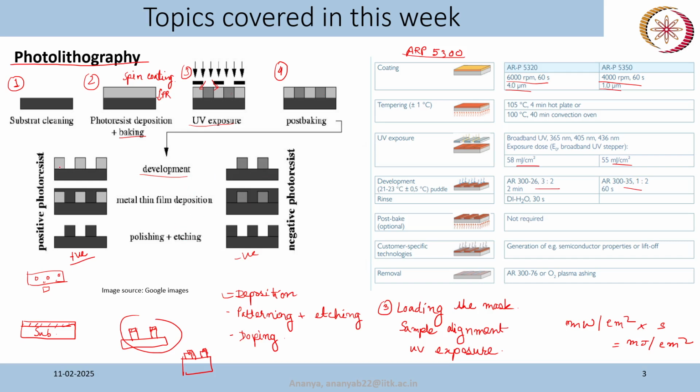So this is one kind of patterning, so patterning is already done. Now ultimately you don't want photoresist, you want some material, say you want some metal deposition on top of your substrate. So say here you do a metal thin film deposition. Okay, so this film will be something like this. This portion is metal. Now what you do is etching.